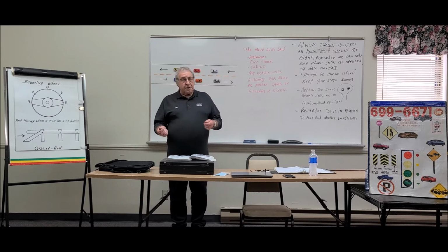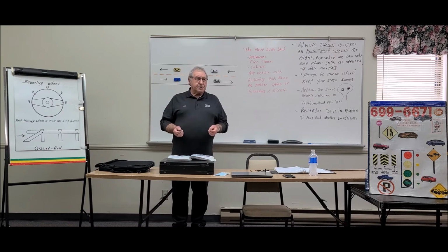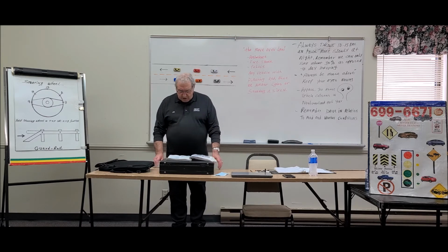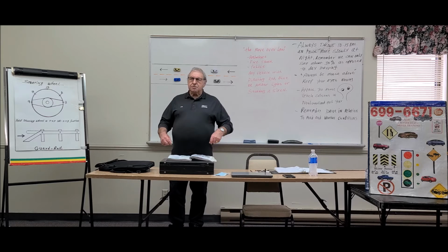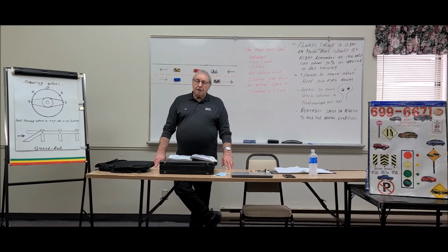So when you go somewhere else, probably another store or parking lot somewhere, you do the same thing again. So eventually you're wearing your tires needlessly by that dry steering, scuffing the tires from right to left or left to right without the vehicle's tires even rolling ever so slowly. So again, as I say, once you buy your own car and you have to buy your own tires, and when you're parking in particular, we're doing a lot of turning of the steering wheel.